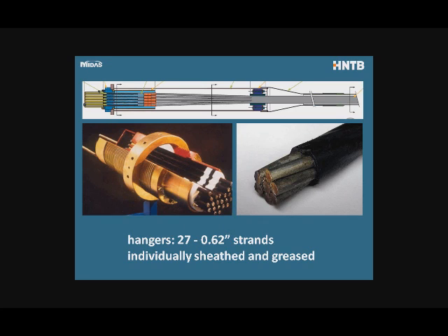And then they're anchored with wedges in an anchor plate. So similar to a post-tensioning strand. The whole anchor assembly is threaded, and there's a ring nut to adjust the whole anchor. And in the upper view, you can see the transition.